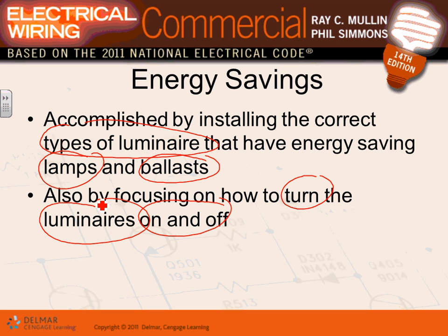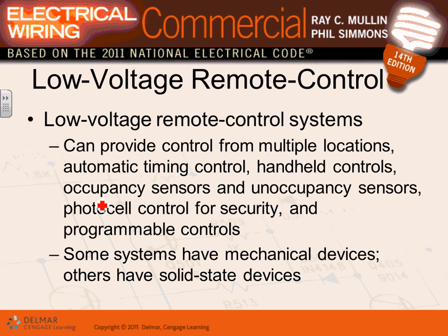You need an efficient lamp, efficient ballast, efficient fixture. That goes without discussion. We bought it. Installation is efficient too. And the last thing you need to do is be able to efficiently control this efficient fixture. Does that make sense, guys? By having a low voltage control system on them to meet the energy code. So that's what this chapter is all about.